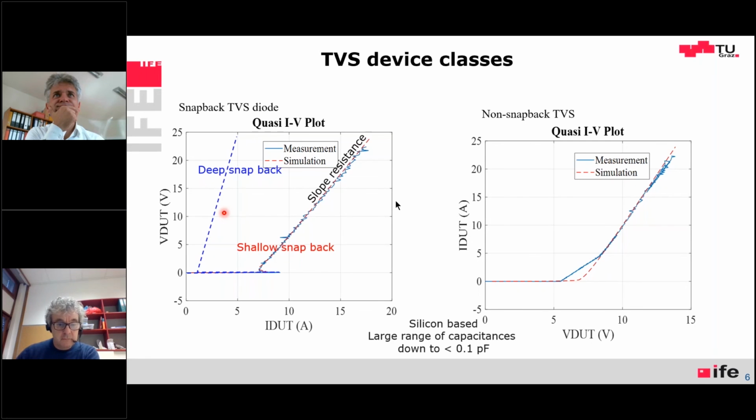There's one question now. What type of ESD protection would you recommend for RF amplifiers? The problem is that they are often sensitive to high voltages, but the output signal might be influenced by non-linear behavior. That's a big story. We work quite a bit on this question of harmonic generation, and there are two classes of harmonic generation. One is by nonlinear devices like ESD protection. The other is metallic contacts. Little clips or some connectors cause harmonics.